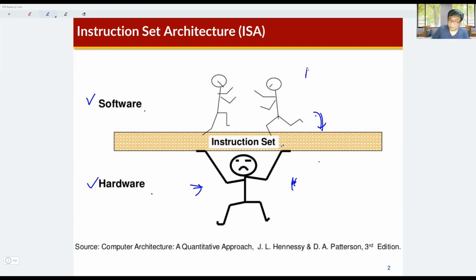So this is the application, and then this application is compiled and generates instructions like add, sub, multiply, and branch. Actually, an instruction just defines the result of the instruction, like add R1, R2, R3, and then the definition of this add instruction is R1 equals R2 plus R3.